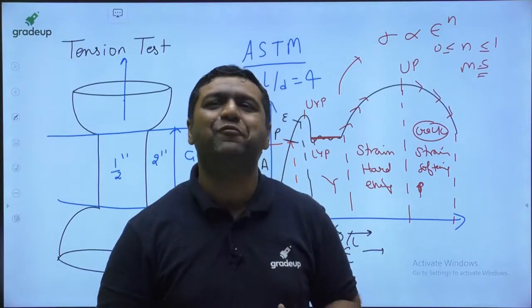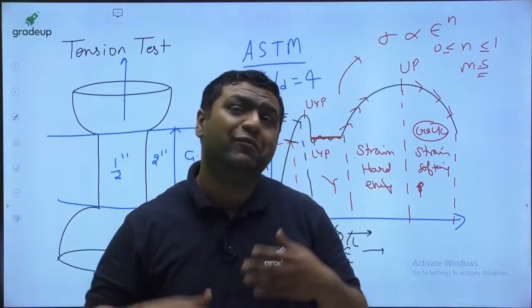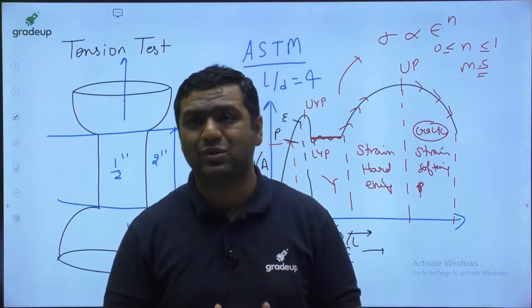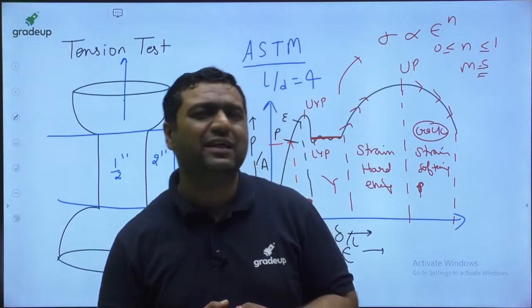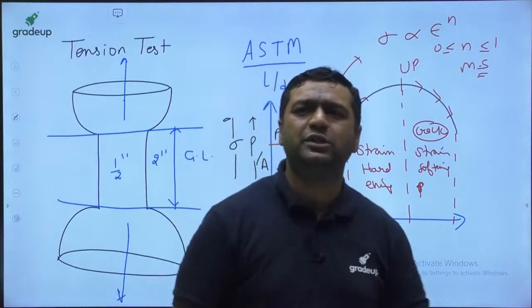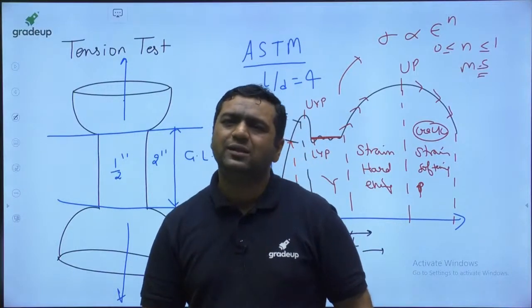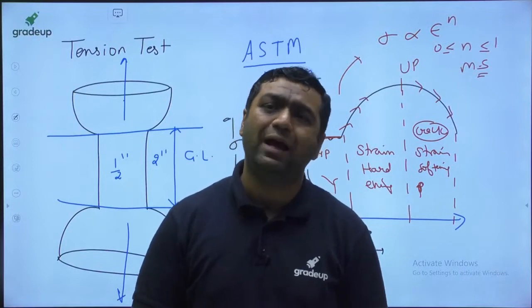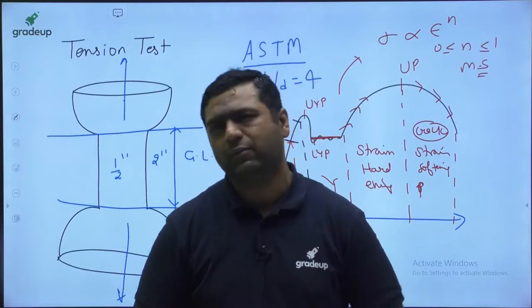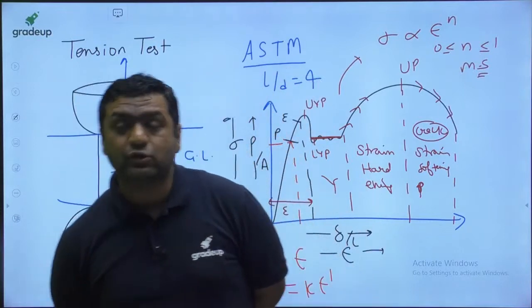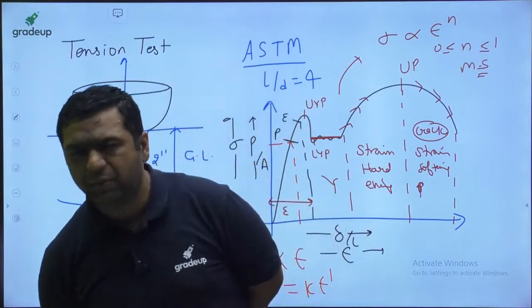In the same way, when you try to improve the properties of low carbon steel, it will not show a good response. When it is not showing a good response, we say it is less responsive, and the technical word used for less responsive is mild. That's why we say low carbon steel is mild steel, because the response to heat treatment is very, very poor. If I am teaching you something, asking you something, and your response is poor, I will say the batch is very mild.